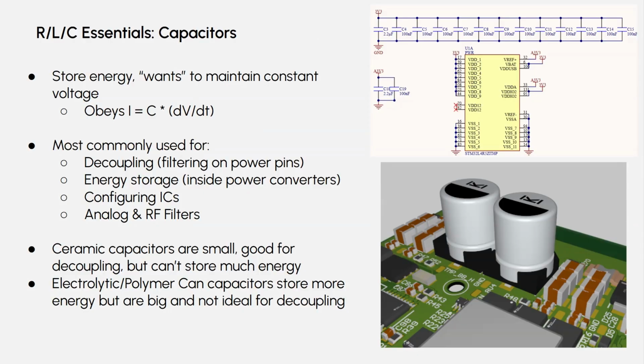And what you want is, when your microcontroller needs to do some analog calculation or read something analog, do some digital calculation, it's going to pull power off the digital line. And you want to make sure there is basically an energy storage device close by where it can source that power from quickly. Because if you have a really distorted, noisy supply that's far away through a USB cable and your microcontroller asks for some current to do a calculation, there's a high chance it will potentially glitch and either not work, corrupt your program, etc. This is really in the worst case.